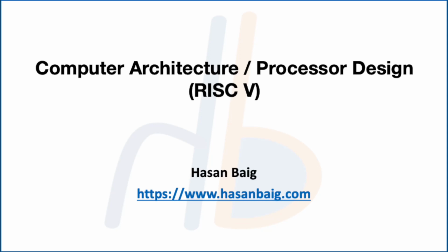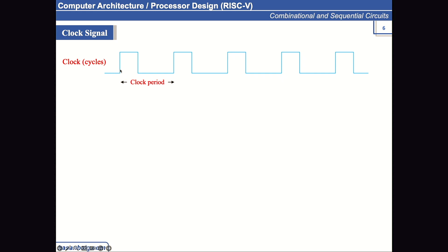So how does the clock signal look? It is just a pulse train of high and low pulses. It looks like you always read the clock signal from left to right. So it is going from left to right, and this is considered as logic 0, and this is considered as logic 1. Now this logic 0 may correspond to a voltage level that could be 0 volts, and this logic 1 corresponds to a high voltage level, let's say 5 volts.